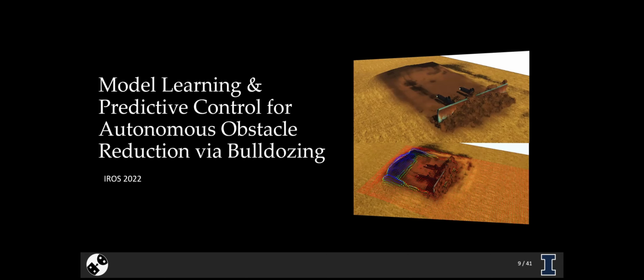I will go through it briefly, but essentially here we use these simplified models in simulation of a bulldozer that you see depicted over here, where the blade can engage with the ground. There's no chassis, it's floating and invisible. The basic idea here was, can we collect data from human operators as they're performing an earth-moving task like berm removal? And then can we use that to learn a model of the earth-moving dynamic itself? How does the terrain move when the blade is engaging with the ground? And what does the blade do when it stalls out?